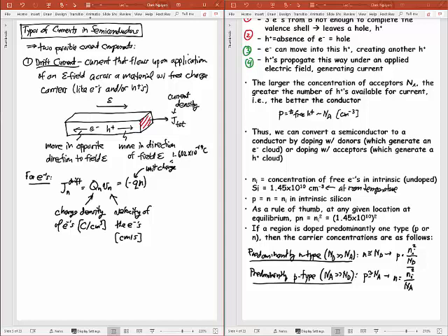And this then has to be multiplied by the velocity of the electron. So the velocity we normally write as minus mu n. It's minus because the electrons are moving the opposite direction, right? So my x-axis is this. There's the positive direction of x. So anything moving in the opposite direction is moving in a negative direction. So I'm saying minus mu n here times the electric field. Mu n times electric field becomes my velocity.